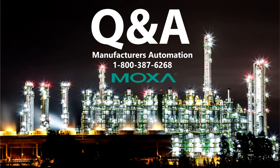It should operate with no problem there. The tests we ran were over 50 degrees Celsius, so that's pretty much our best practice number. I can answer for Moxa's HMI and say that they will operate reliably slightly above that temperature grade, but that's the line in the sand that we drew, and so that's well over your operating temperature. Should not be an issue. And what was the second half of the question? The expected life of the HMI.